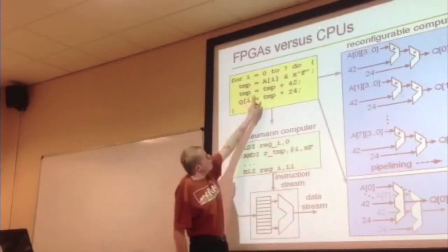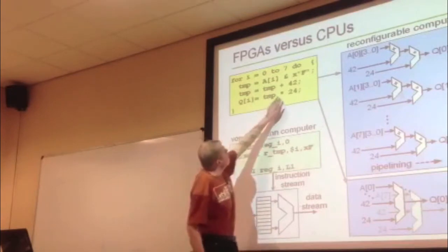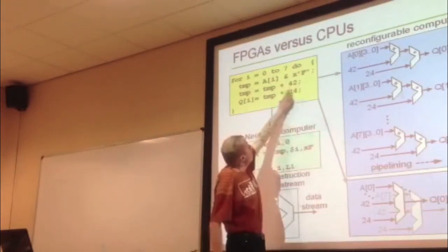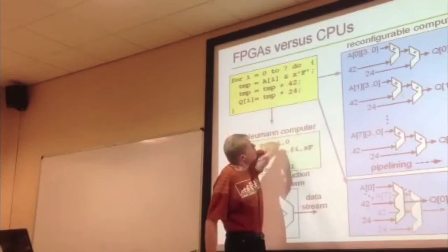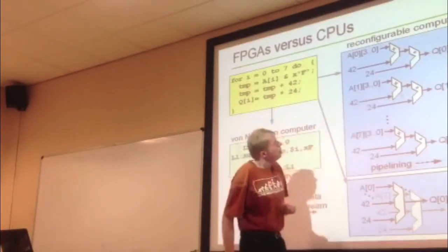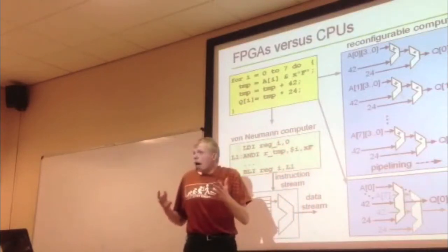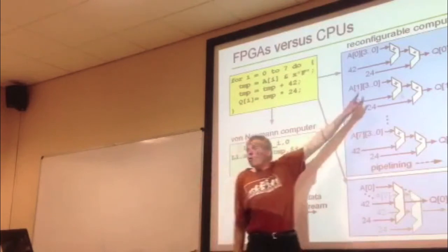Okay, this works fine, but if you go for an FPGA, you typically would do it in a different way. What you do is you start to do something like pipeline processing. So for example, here is a Boolean function where you just want to take the least significant bits. From a vector, you just pick the least significant bits. And this is not necessarily a function. Why? Well, this is just wiring.